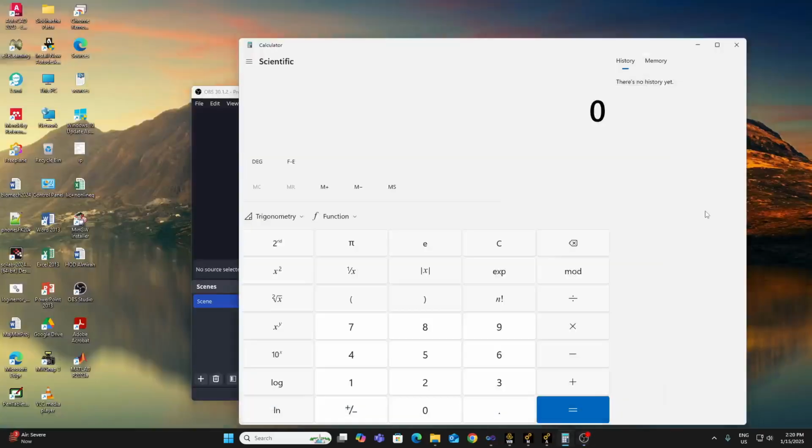Okay. I just forgot to mention one more thing. We observed from the simulation that the descent of the indenter was 0.7 millimeters. Okay. Now let us try to evaluate the Brinell hardness number of the material, in this case mild steel, using the depth of indentation, that is the descent of the indenter. Okay.